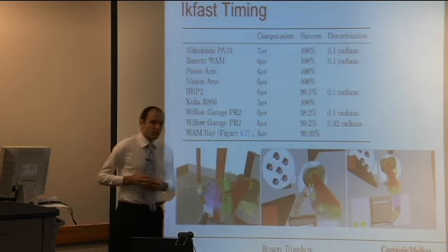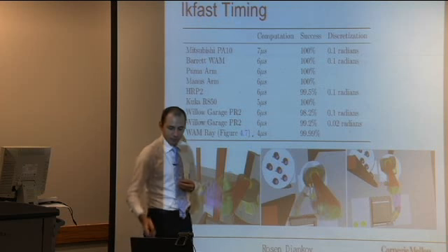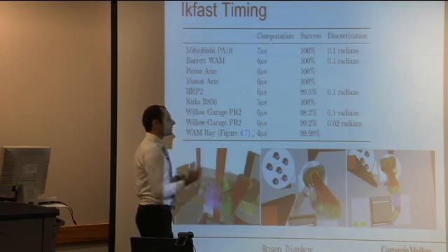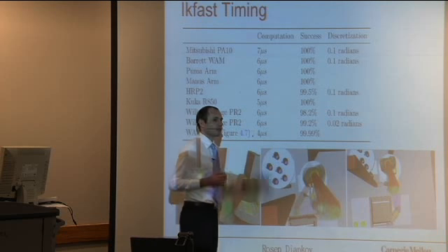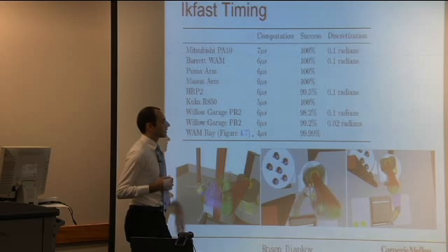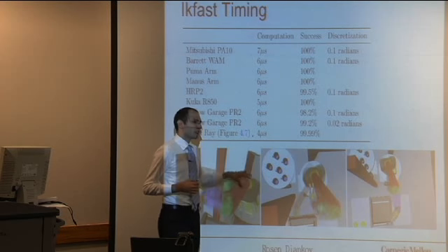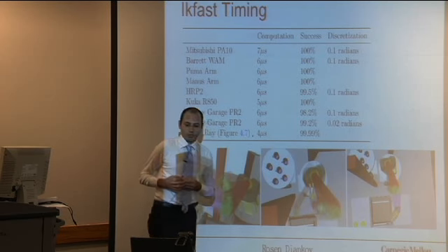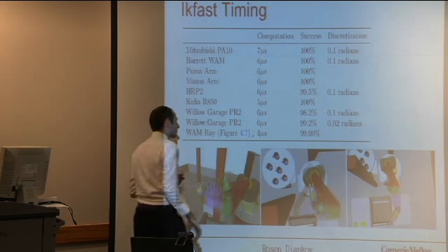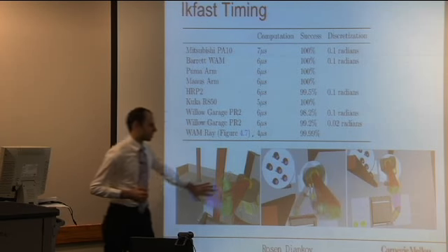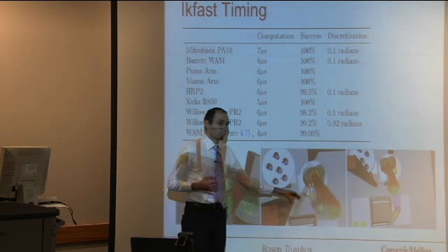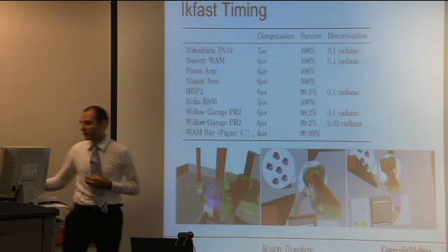So we ran various computations on the speed, and it turns out that most of the time it can complete in 5 to 7 microseconds. And depending on whether you have extra redundant degrees of freedom, we discuss how you can handle these degrees of freedom appropriately. You can see some solutions here of how you can efficiently explore the space of all the inverse kinematics solutions that are collision-free from the environment.